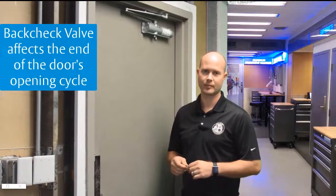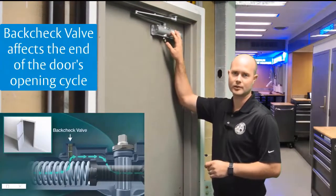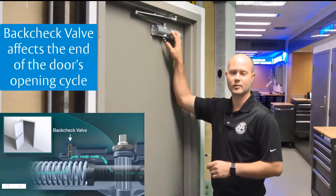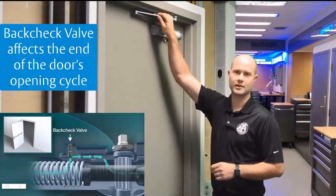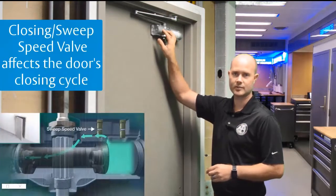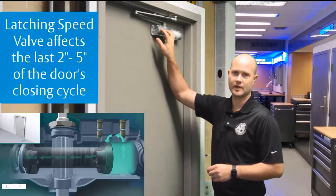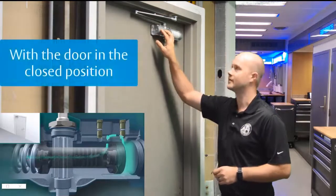On our back check side, our back check valve is here, noted by a B on our closer body. That prevents the door from slamming into a wall or a window, and prevents wind from catching the closer and pulling on the arm unnecessarily. We're going to adjust that. Next, we're going to adjust our closing speed valve or our sweep speed valve, and also our latching speed valve. And we'll be able to demonstrate exactly what those valves do and how they function.